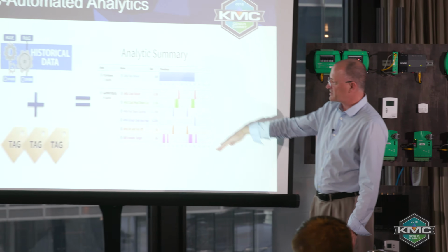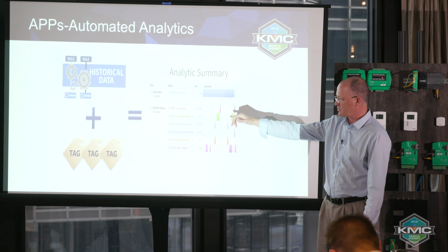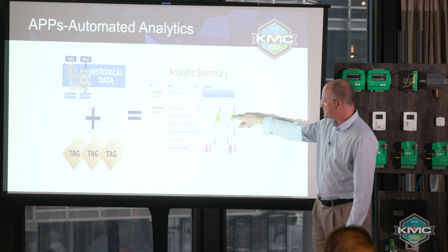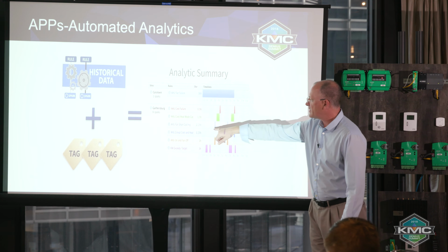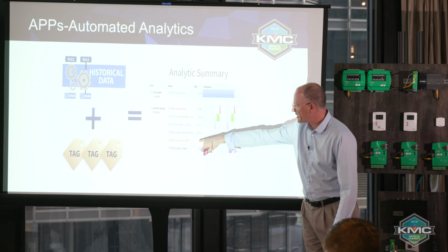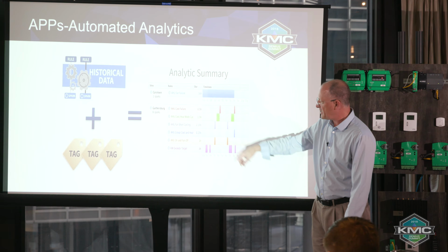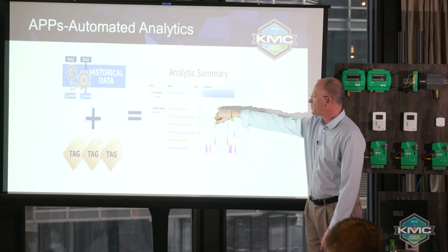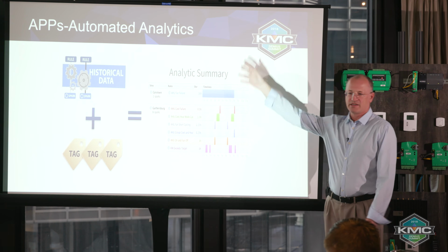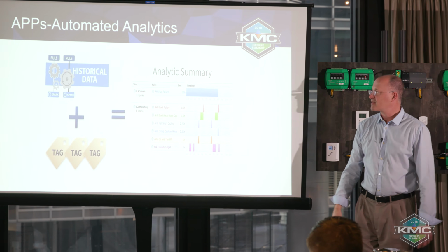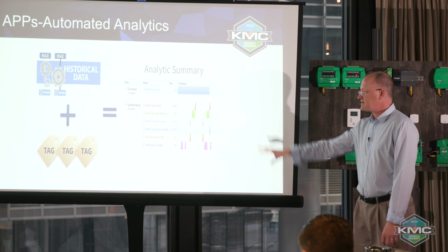And then you might get a visualization of 4 or 5 rules and when the rules were broken. So there's our simultaneous heating and cooling. Here's a short cycling. Here's the air handler was running when it wasn't supposed to be. Here's a cooling failure. And then behind the scenes there'd be a set of rules. Cool. So that's the hope.